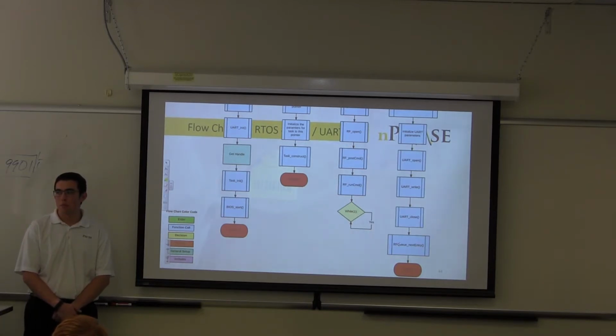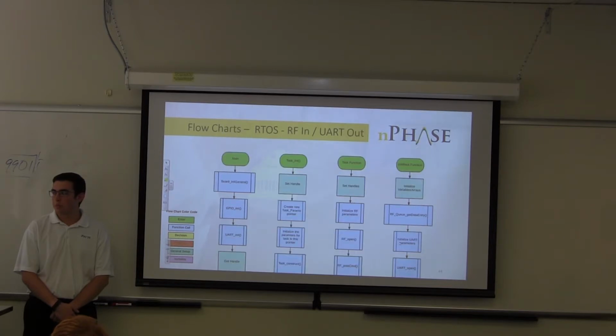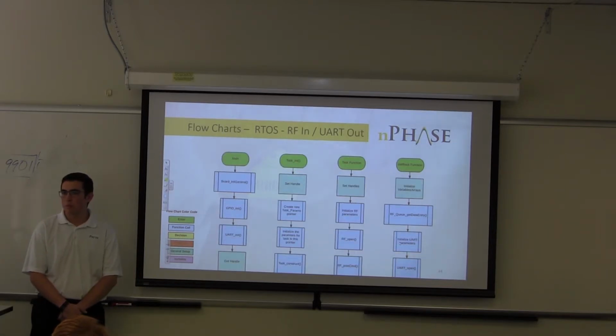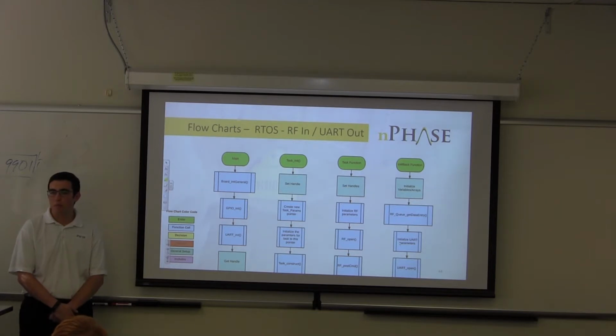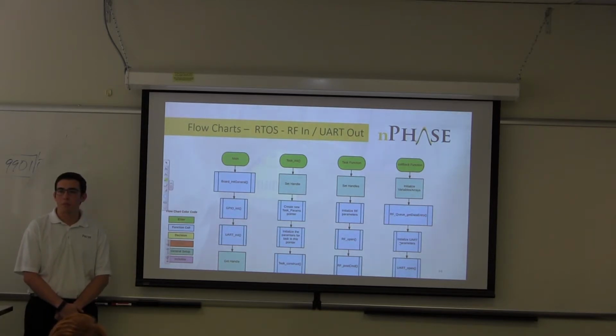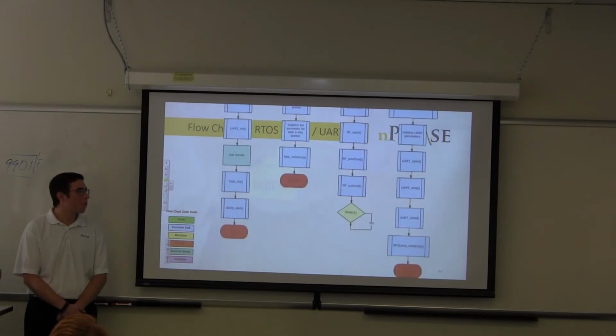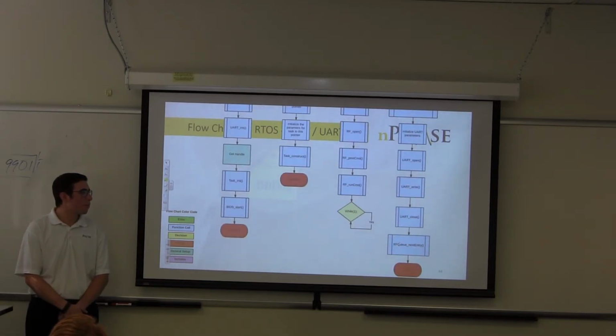So when we receive over RF, we're going into this callback function, and here we initialize our variables and arrays, and we call this RFQ to get our data, and we initialize our UART, open UART, and write that data out to UART to our serial interface on our computer.